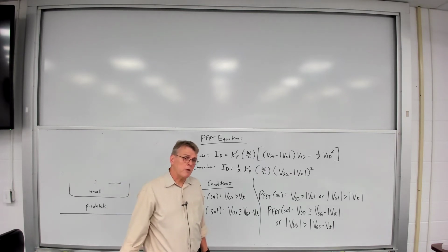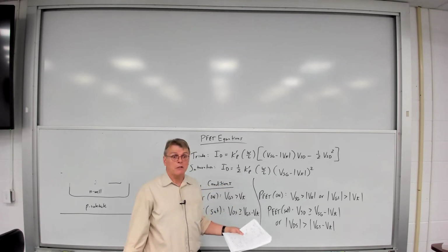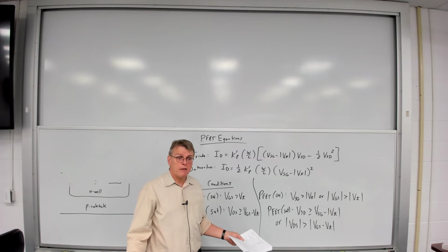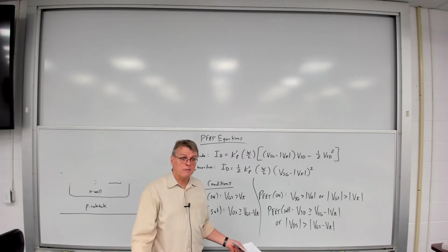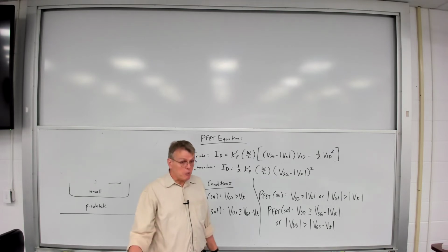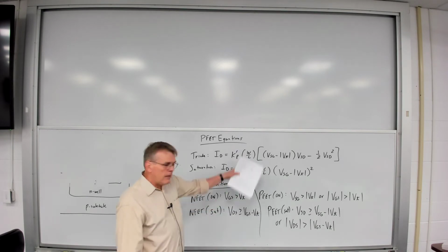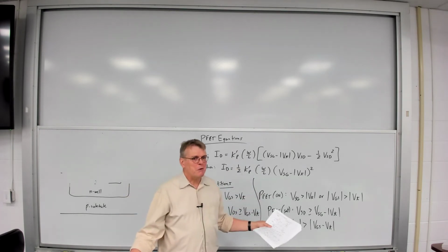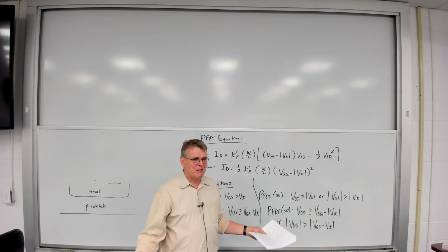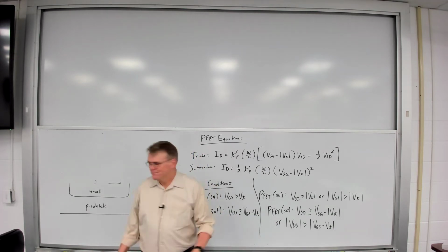Well, it depends upon the circuit and how you connect the circuit. Typically you want VGS or VSG to be a constant voltage because you're trying to set a bias, right? So it depends upon the circuit you're trying to build. But yes, it's certainly possible to do it that way, but it's a function of what you connect it to. As we start learning how to bias and analyze MOSFETs, this will become a lot clearer to you.